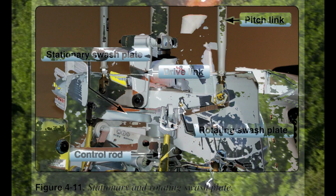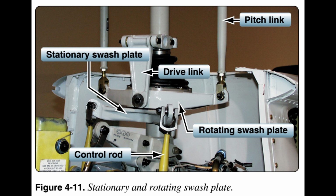Swash plate assembly. The purpose of the swash plate is to convert stationary control inputs from the pilot into rotating inputs which can be connected to the rotor blades or control surfaces. It consists of two main parts: stationary swash plate and rotating swash plate. Figure 4.11.